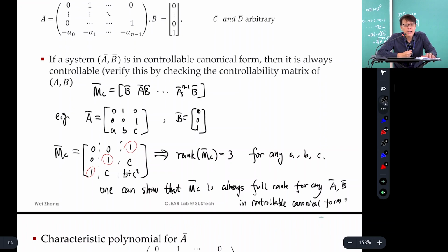It turns out designing to assign eigenvalues of a closed loop system can be done very, very simply by hand, even by me, okay? I'm really bad at calculations. By hand for a controllable canonical form system. Everything you can write on a piece of paper. And for any controllable system, you can always transform it into a controllable canonical form through a change of coordinates.